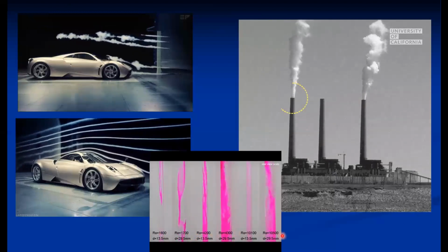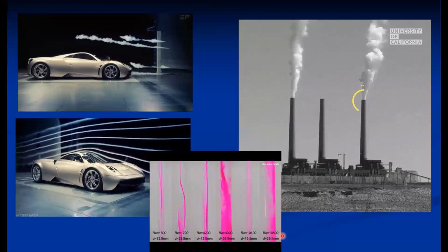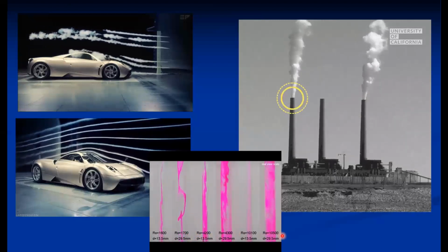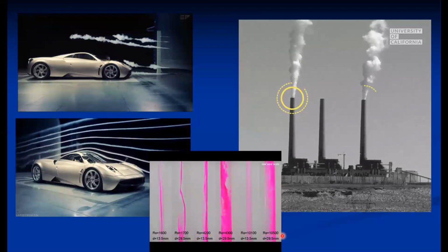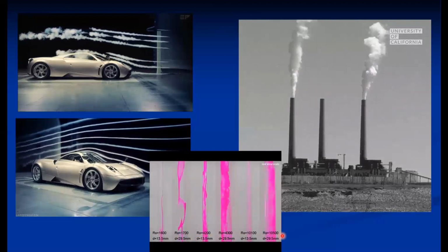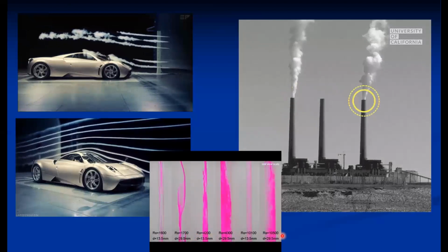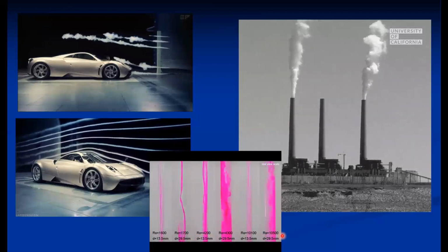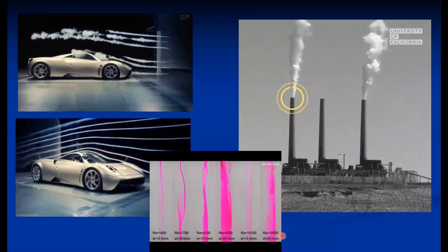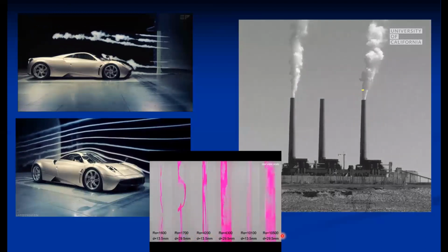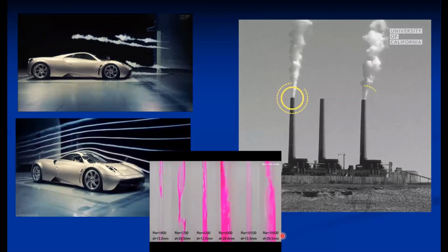There is a separate experiment that uses the streak lines. With the color dye, we can recognize whether the flow is laminar or turbulent. So this is about the streak line, which is generally used to trace the motion of the fluid particles, like in a wind tunnel also. There is no specific equation for the streak line, but there are specific equations for the path line and streamlines.